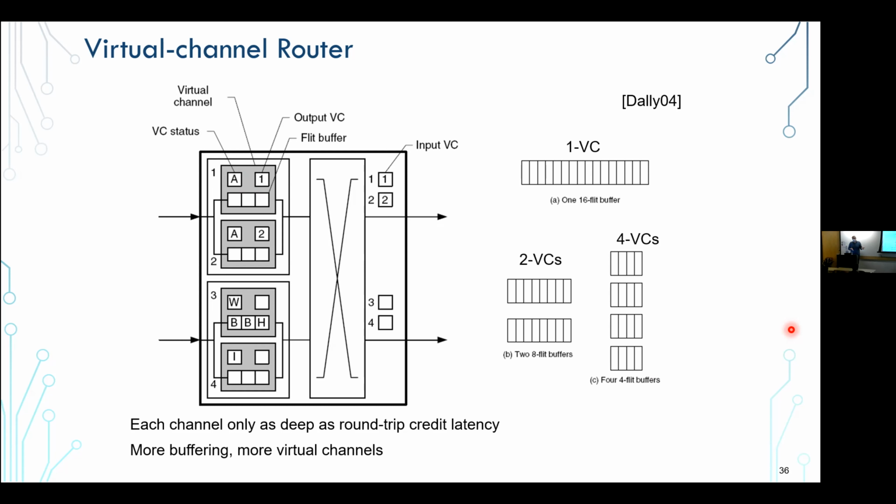That's in networking called Little's law, and it applies to kind of anything in networking. The fatter the pipe or the channel, and the longer the latency, the more you have to store to be able on either end to not lose anything, right? So that's kind of the point. So if you think about how this is scaling, the faster the network I want to have, and the longer the latency I have, if I'm building a bigger chip and the space between routers is bigger, the more buffering I need. So my routers get more complex, right? So this is kind of all tied together.